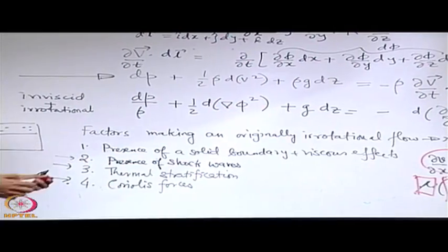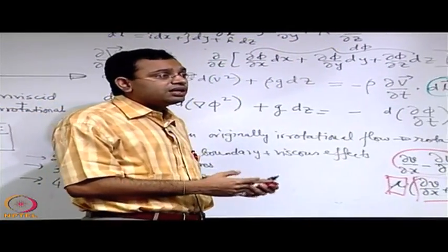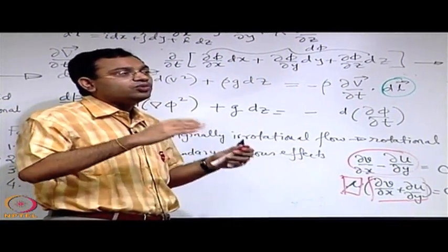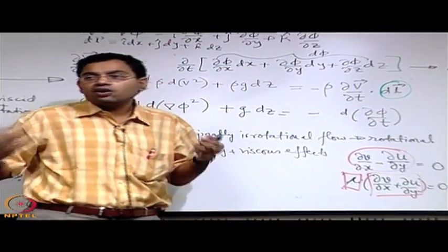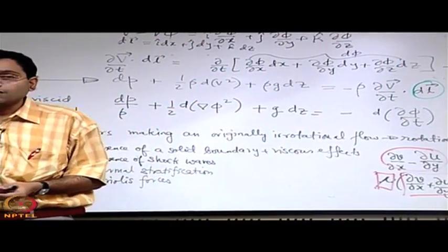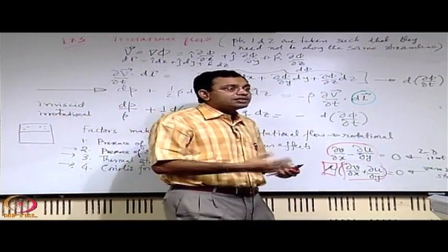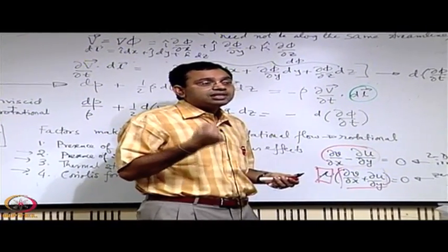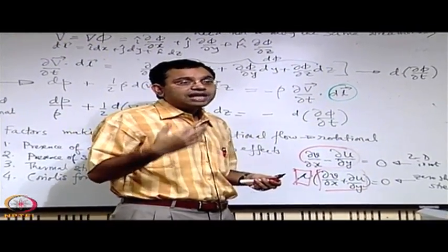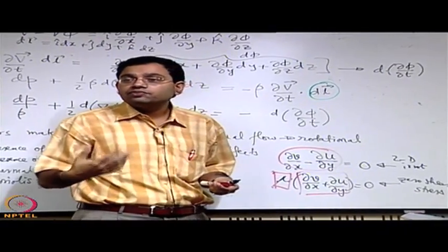Now if you think of the velocity field, it is not exactly like a force field, but you may think of it analogously, because it is also a vector field. So in a velocity field, what could create a disturbance in the conservativeness is the presence of a dissipation, and that dissipation is through the mechanisms of viscosity.